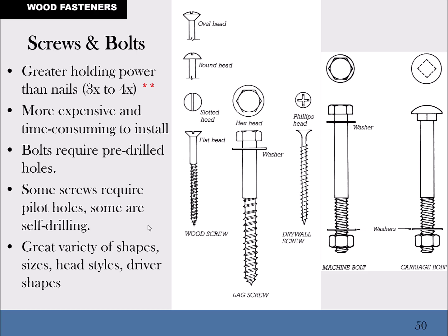And then the bigger the screw and the more aggressive the screw pattern, the more holding power they can devise in there. So you get lag screws. They are big, heavy shaft things. You always have to pre-drill for them. If you didn't, you could split the wood, is why I'm saying that. You could find a way to screw it in there, but it could split the wood and start damaging whatever you're trying to save.